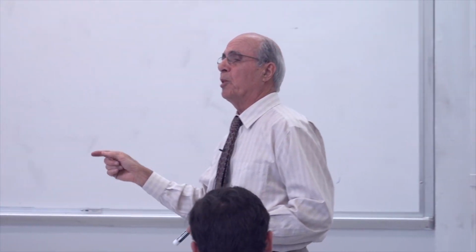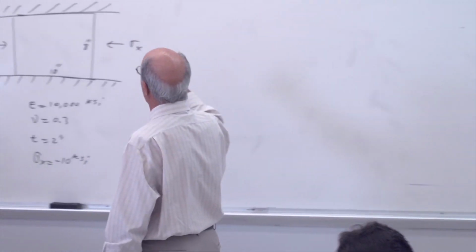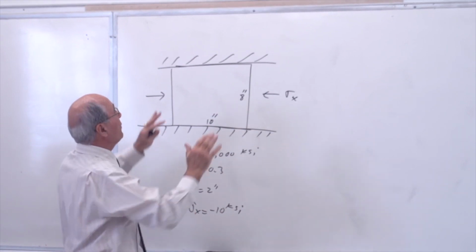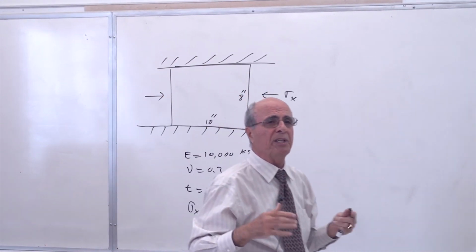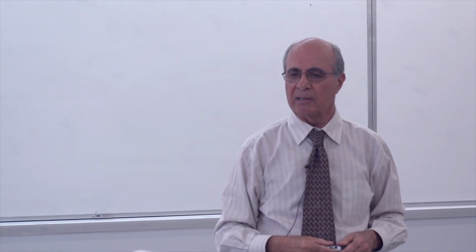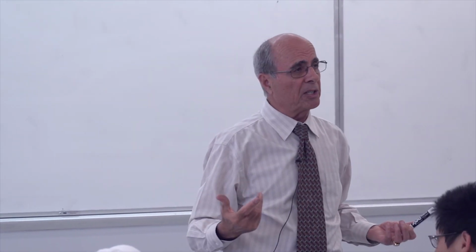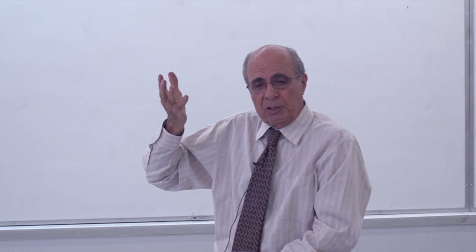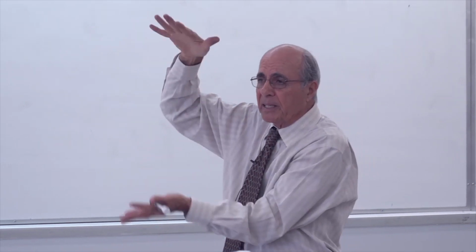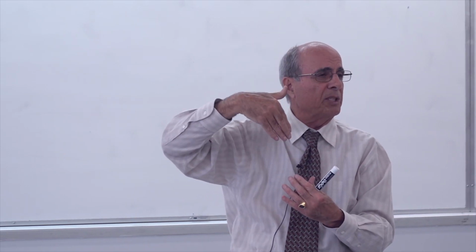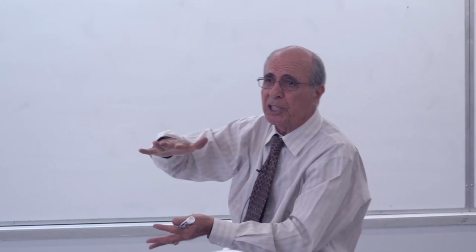The major part of this problem, this has only one-dimensional stress. It looks like there is no sigma y, yes or no? And if it was free, that would be the case. If it was free, you only having one-dimensional stress, you can treat that like chapter 1. Is that correct? Delta equal to PL over E and et cetera, et cetera. Is that correct or not? Yeah? However, this is not one-dimensional stress because of this pressure, the plate wants to change in the y direction and you are preventing it from there. So therefore, there should be a sigma there. Yes, it's the form of compression. Everybody can feel that. Yes, it wants to go up. You have to push it back down.